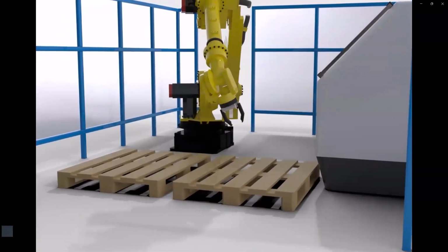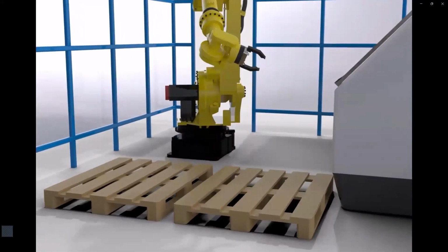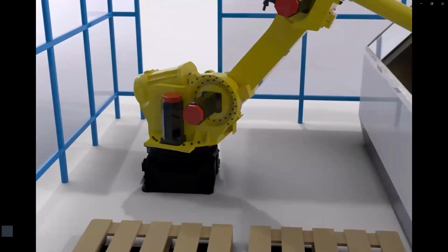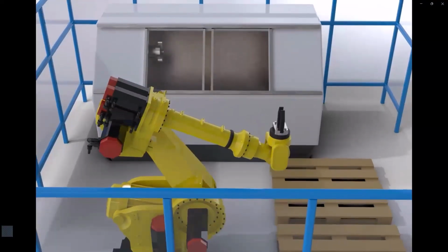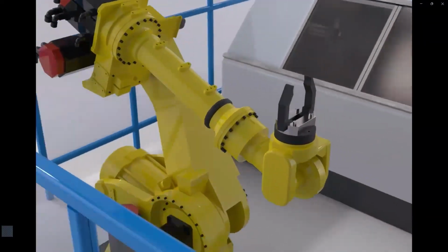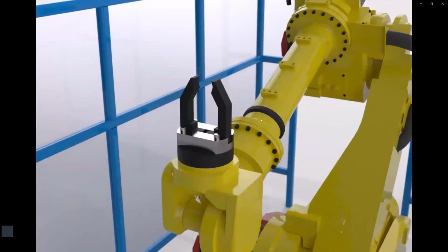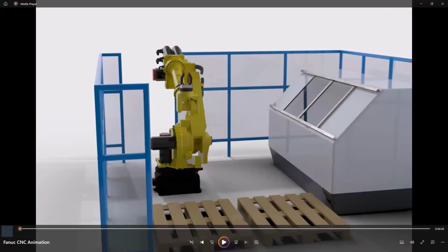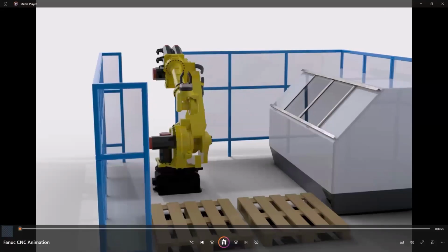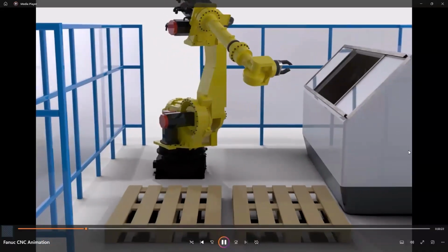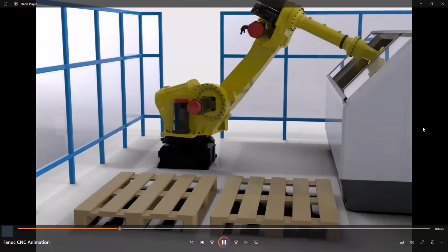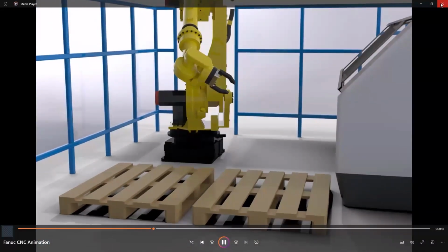What I did is I used Make controller to create the animation, and then I brought that into motion study in SolidWorks, exported that out and brought that into Visualize, and then further animated the camera and things like that. So the short answer is yes, you can do amazing videos with SolidWorks Visualize.